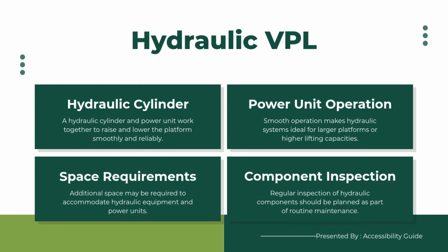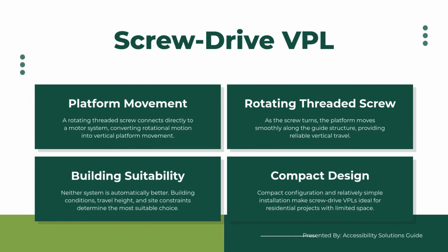4. Which elevator type is suitable? There is no single elevator system that works for every existing building. A machine room-less, or MRL, elevator can be a good option when there is no space for a traditional machine room. It is commonly considered for apartment buildings, offices, hotels, and other modernization projects. A traction elevator can provide smooth operation and good energy efficiency. It may be suitable for multi-floor buildings or projects with higher passenger demand.